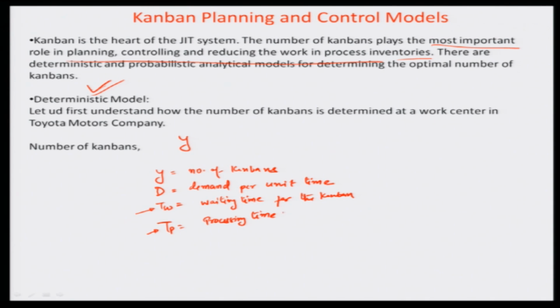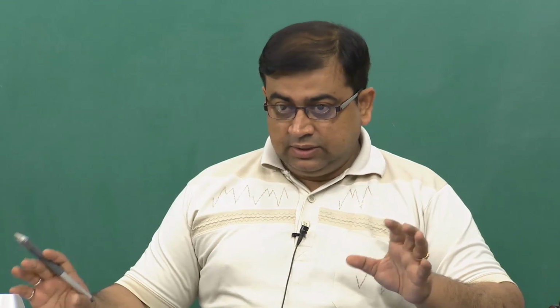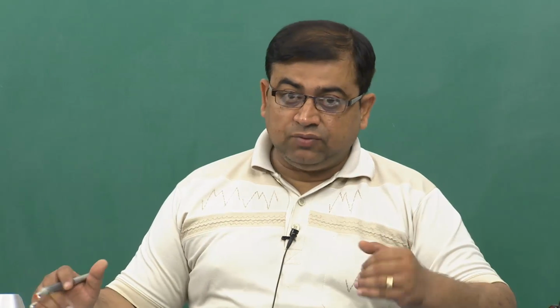And A being the container capacity, that means whatever number of parts are coming in one bin or one container. We also introduce a policy variable here, alpha, which is actually the shock absorbent mechanism that you have in place in a Kanban. You can always over plan a little bit or lesser depending on the regularity of your supply schedules. So, you try to vary this alpha to the minimum possible to have an overstocking situation or even a zero overstock situation.